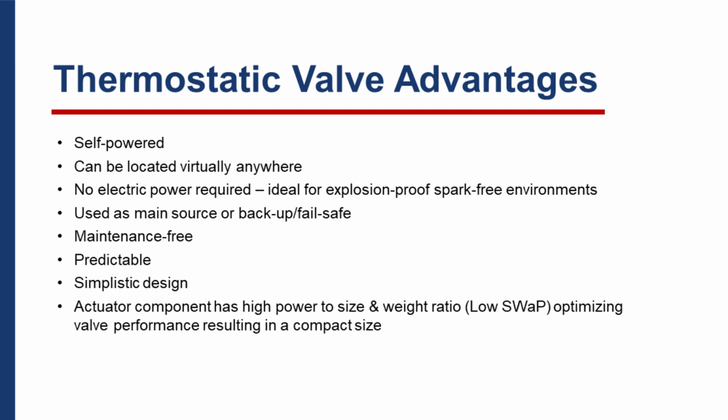So the advantages of thermostatic valves. The main advantage is that they're self-powered, which means they can be located virtually anywhere. They don't require any electrical power, ideal for explosion-proof, spark-free environments. Used as a main source or backup failsafe for powered devices. Virtually maintenance-free, very predictable, very simplistic design.